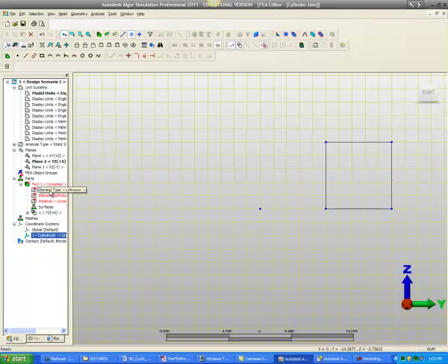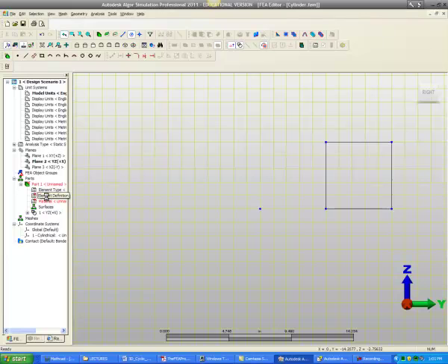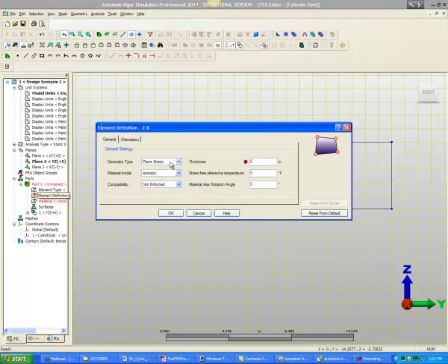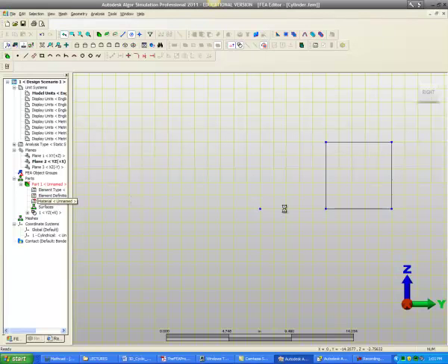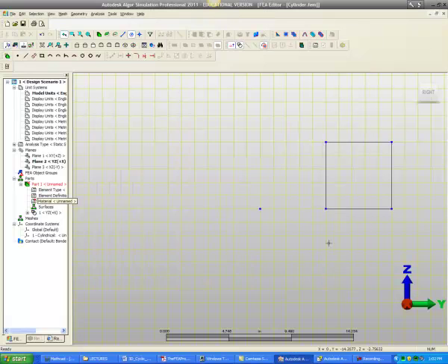Alright, so now let's set up our element type. Remember, you go to 2D. It's thinking for a moment. And for element definition, the geometry type is not plane stress. Make sure you set it to axisymmetric. I'm going to leave everything else as it is. Thickness, Autodesk will automatically use a 1 radian thickness. Okay, so let's stick with this. Let's go OK. For a material, let's just use a steel. I'll go with AISI 202 stainless. Use whatever material that you'd like to use.